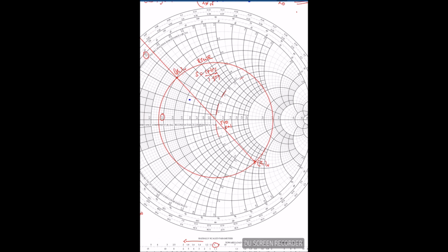So, on the SWR circle, I take the normalized admittance and move along the R resistance circle till I reach the r equals 1 circle. This is r equals 1. At this point, half of the work is done. I moved my load admittance to the matched admittance condition, that is 1. So here I move this point to here.